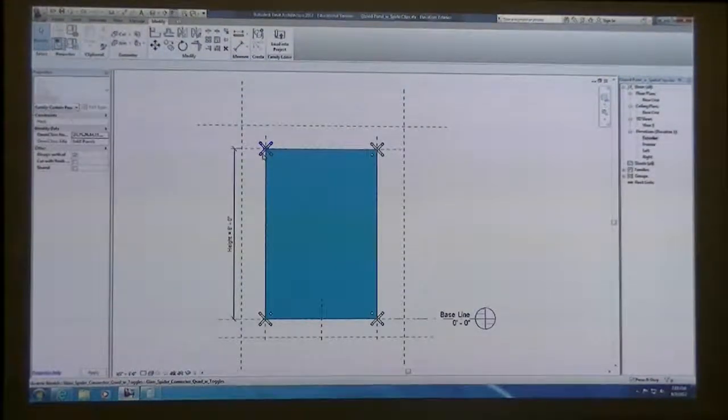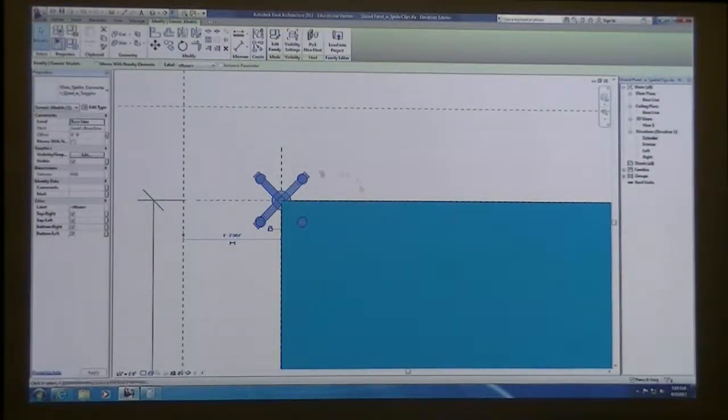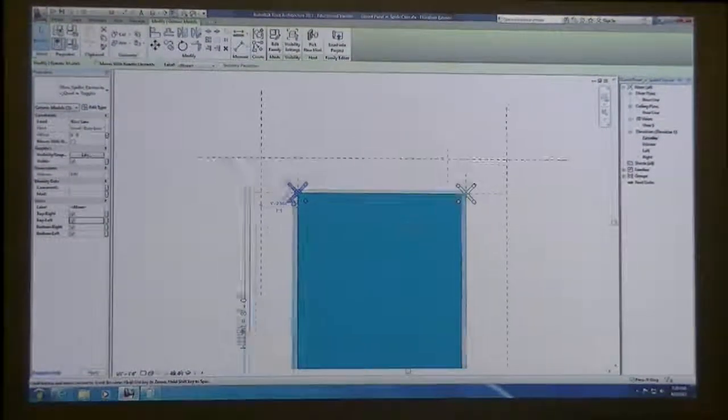By the way, what I'm not really going to explore further is at the very beginning of the class, we set those toggles for this particular spider clip. And if you click on one spider clip, you'll see to the left you have your top left, top right toggles. And so if you start playing around with the check marks, you can start to see how you can toggle on and off. And of course, I'm actually looking at it the right way. Bottom left turned off. Yep. Top left. So you can see how just by setting up those yes/no parameters, we can toggle that on and off. And then later on, you can get more detailed if you really wanted to toggle if this is going to only have a 1 prong or a 2 prong at all the intersections. You'll drive yourself crazy if you try to get into that much detail at the particular moment.